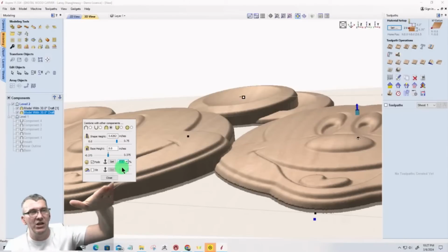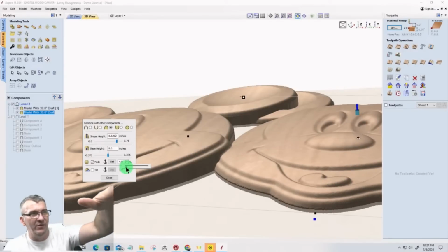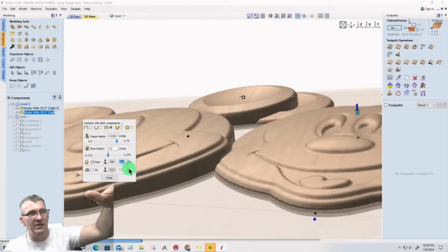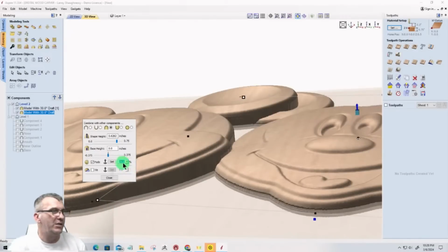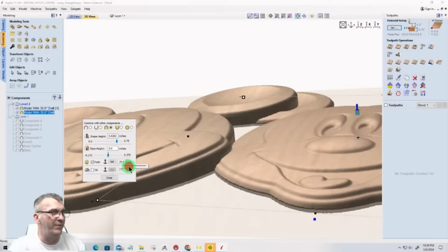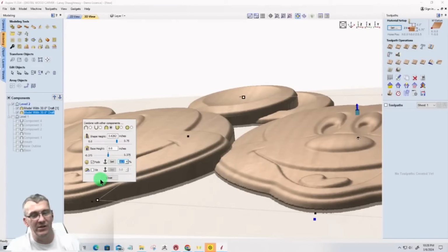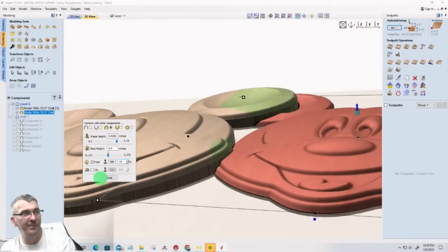You should have seen it lift up. Let's do that extreme again. Let's go in here and let's watch the left side of the right Mickey. At 4% fade. If I change that to 29%, it's going to fade down. It's going to tilt down. So I really only need, I'm going to go 15% of the fade here. We'll just do 16. I'm not going to try to hit 15. I could just type in the number, 15%, by the way, too.